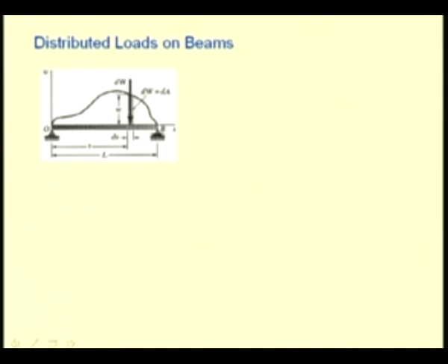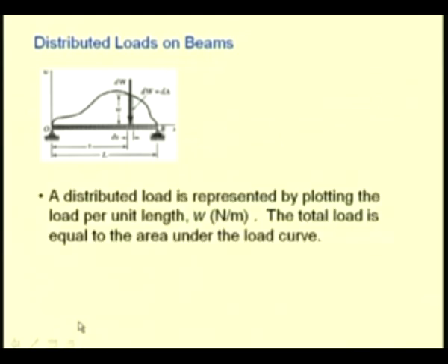So, if we take a small element of the beam dx, the corresponding load is dw, which is equal to the area of this incremental rectangle, and in order to compute the total load we have to integrate to find this area.